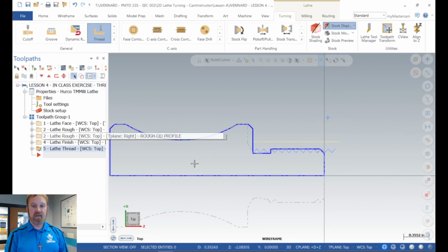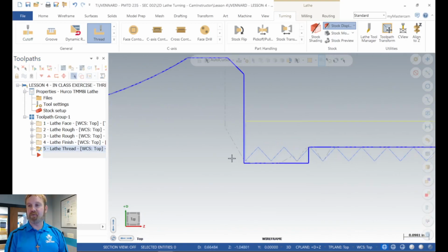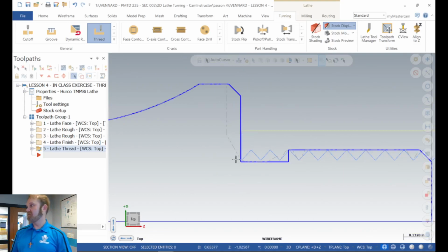Maybe you can't, but if you look at it closely, you notice that basically it's programming the distance to the thread point, right? Well, if that insert's an 1/8 inch wide and goes down to your thread point, it's going to go. So a lot of times what we will do out here, we'll set the tool up, we'll touch off the leading edge of the insert, and then we'll basically subtract in Z half the width of the cut, the thread V. It tells you what that width is on the insert information, and then we'll move it over in Z that amount to the thread point.